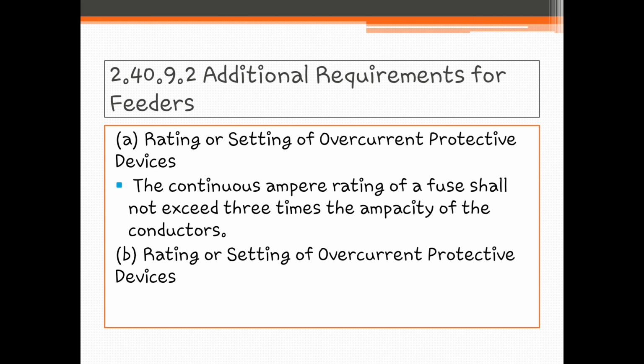The last one, letter B, is feeder taps. Conductors tapped to a feeder shall be permitted to be protected by the feeder overcurrent device, where that overcurrent device also protects the tap conductor. So letter B, guys, is feeder taps.